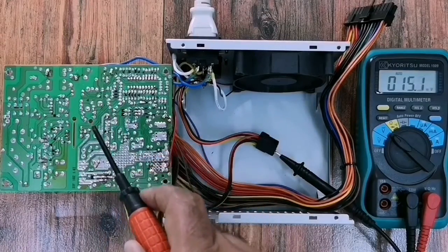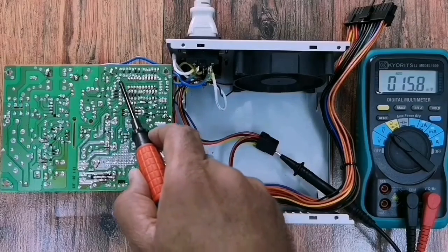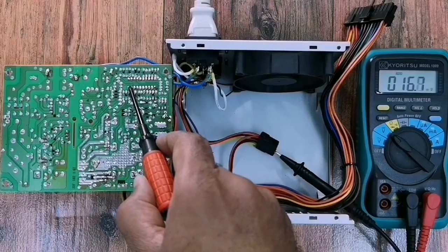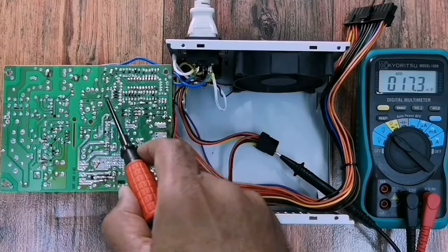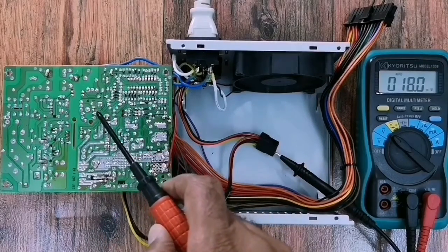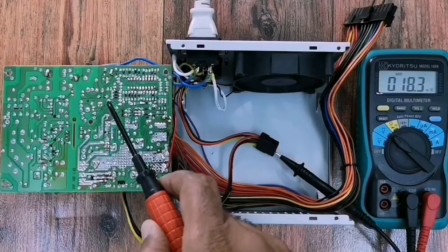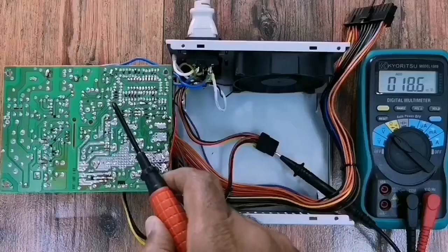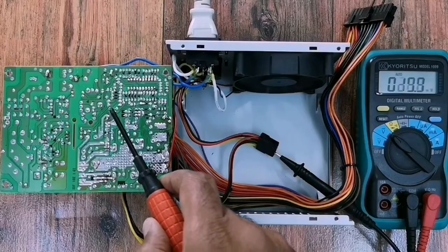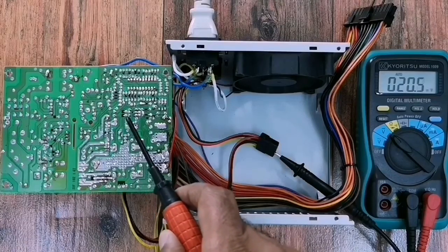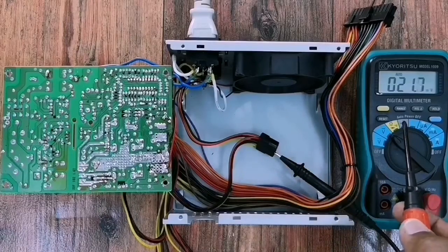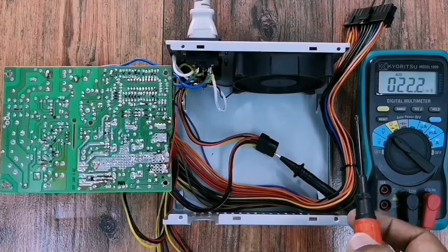What most helped me here was when I saw the pulse width modulation signal coming from the controller IC, and that helped me in taking the rest of the conclusions. I always say the oscilloscope gives some sort of 3-dimension approach in troubleshooting compared to a multimeter alone, which may give 2-dimension only. But at the end, you can make the best out of whatever test equipment is available with you.